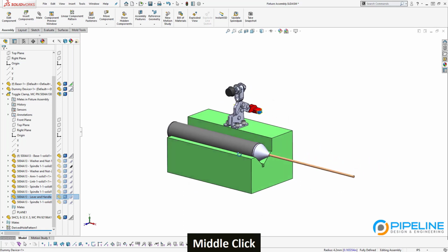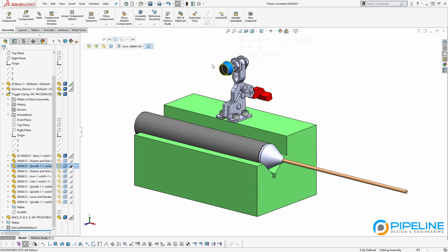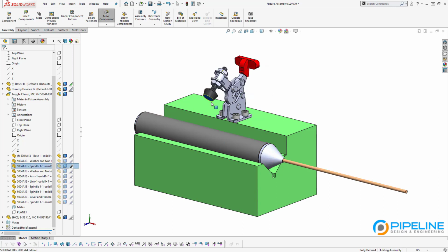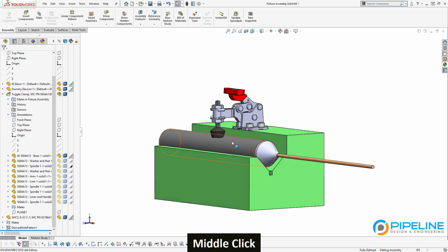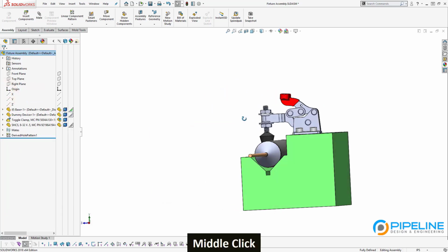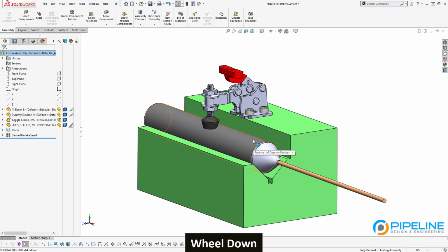And I think actually the final fixture from the real version of this task, we replaced this rubber plunger with a custom shape to distribute the load across the device instead of just leaving the rubber stopper. But there are some projects where we've just had a rubber stopper press on a thing that can withstand that focused force. So those are some of the considerations you might make in a project like this.